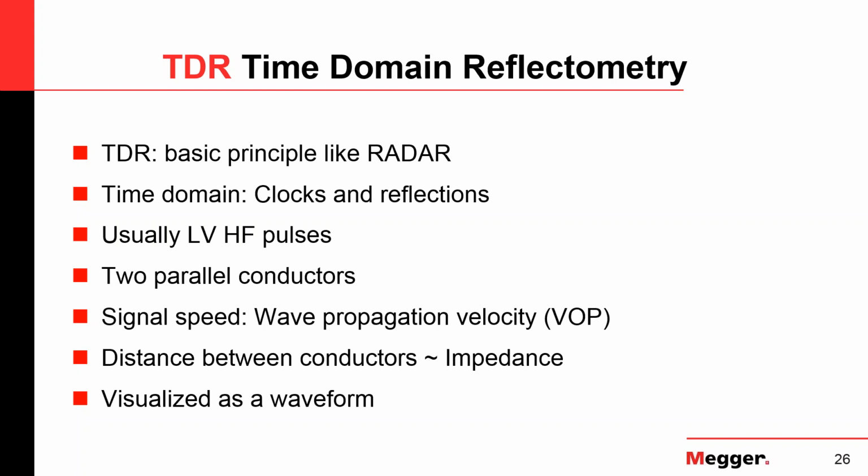And in terms of physics, the TDR works based on, I have two parallel conductors and I send the pulse down. And just to clarify this, the actual electromagnetic pulse, that pulse that travels down the cable, travels between those two conductors. If these conductors are too far away, your 20, 30 volts get diminished, so you don't see much. That's one problem. So you need a fairly close return conductor to make that work.